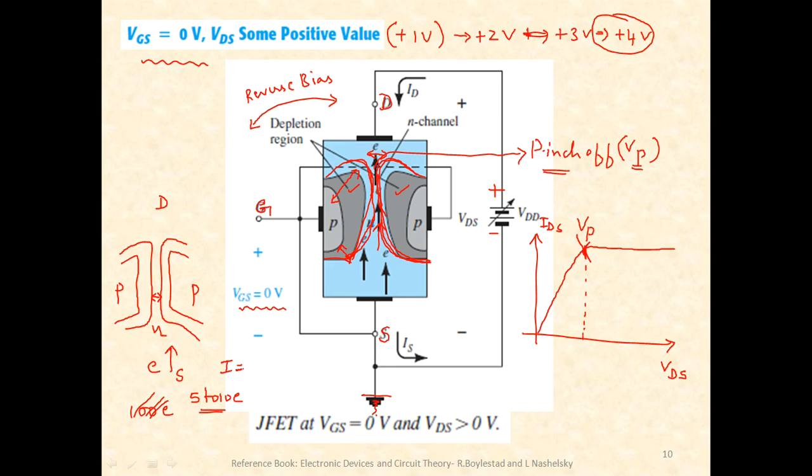Because we know that current can be expressed as I equal to, I is nothing but the rate of flow of charges. So these 5 to 10 electrons gain sufficient kinetic energy, so that they'll be moving from source to the drain at a very high velocity, at a very high kinetic energy, due to which they'll contribute the same current as that of the pinch off stage.